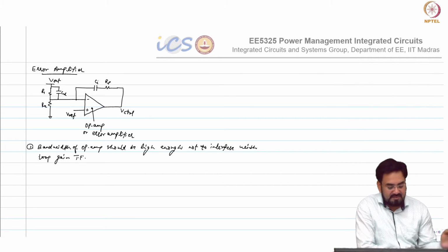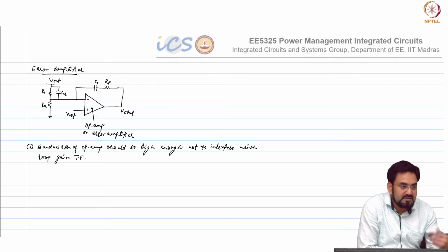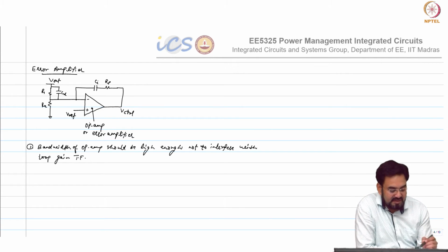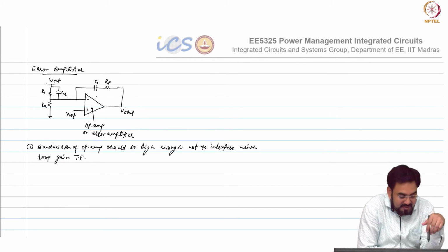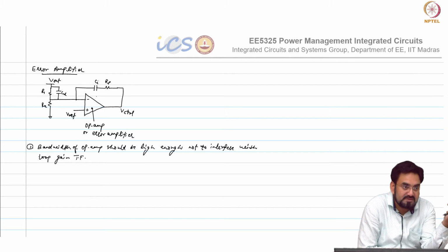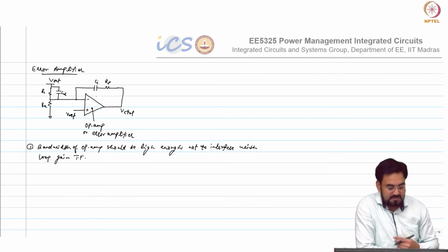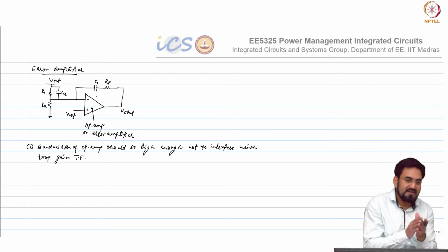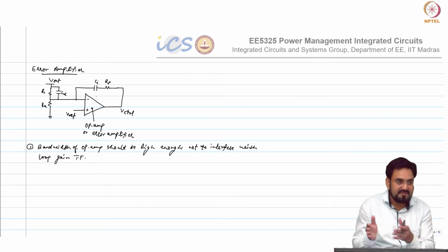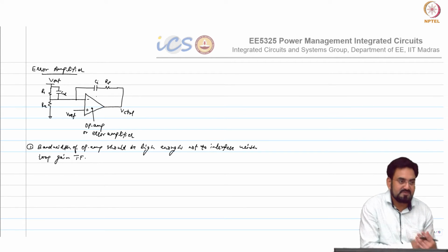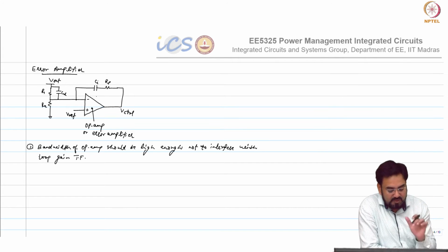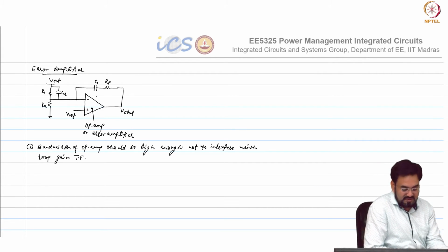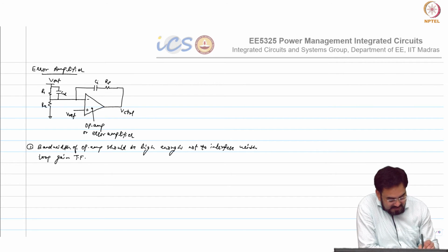So what we want, I mean, we don't want an additional pole from your op amp, because here we are introducing an integrator with 2 zeros, and then on top of that we put 2 more poles, if you remember, high frequency poles, due to noise reasons. So one more pole means, even if it's not inside UGB, but even within, let's say, 4 to 5 times of UGB, still you will get a significant drop in phase margin, maybe 5 to 10 degrees, which is significant. So that's why we don't want the pole due to the op amp to interfere with your loop gain transfer function.